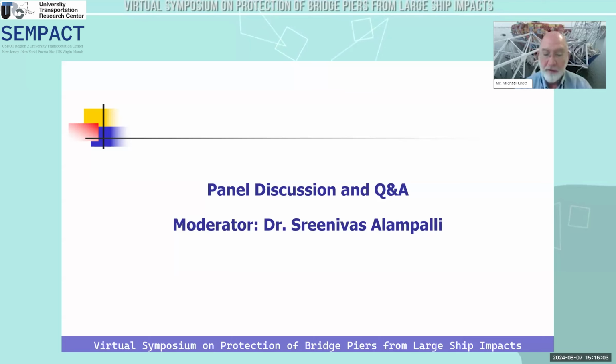This is Mike Knott again. So superstructure collisions can definitely be considered, and there are some guidelines in the code for deckhouse forces. We recently completed a study in Canada where we looked at an arch type bridge subject to mast and deckhouse collisions. With some assistance from others, we developed some equations representing mast collisions and funnel collisions applied to the curve shape of the superstructure as it was moving back toward the waterline.